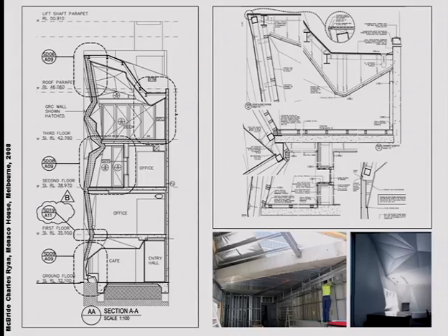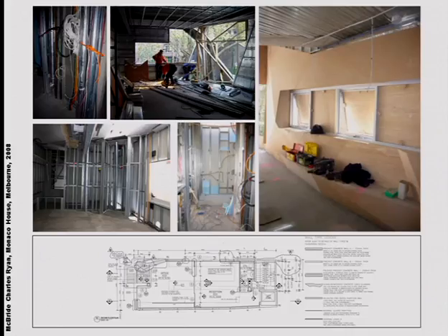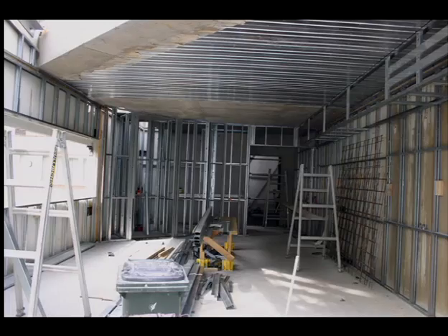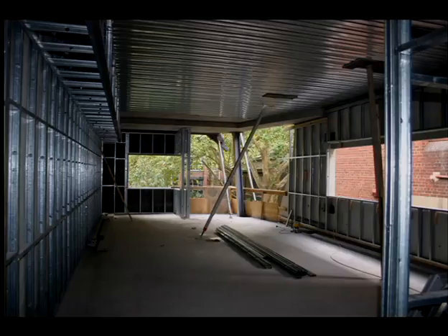And you can design very complicated shapes out of it, like this building you saw before in the cover. Generally, again, all the framing is done out of steel, but also the complicated facade, which is all faceted, is done in the same way. So I'm not going through that, but you see bonders, studs, noggins, jambs, all the elements are there, all comes together also with steel. Temporary props, probably they are pouring concrete.